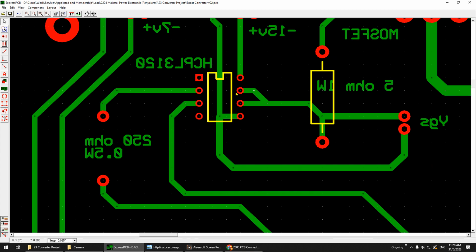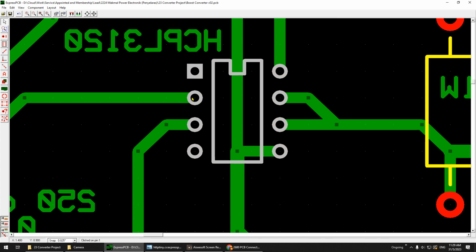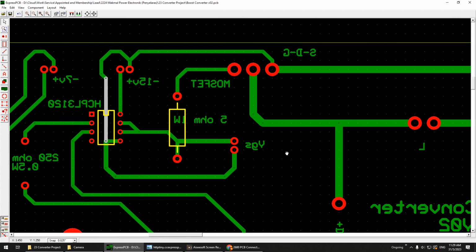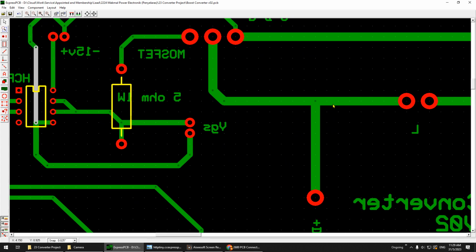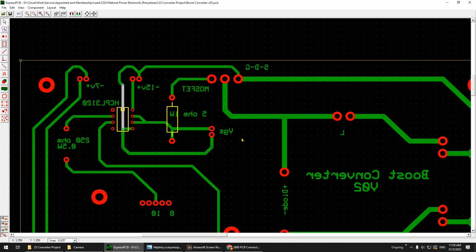But this one cannot do anything because it uses an integrated circuit. When it comes to integrated circuit, you don't have enough space. That's why I do it like this. This one is not very good because you can see here, it is a right angle. Right angle sometimes, during the etching or something, it will eat this area. That is just a limitation.